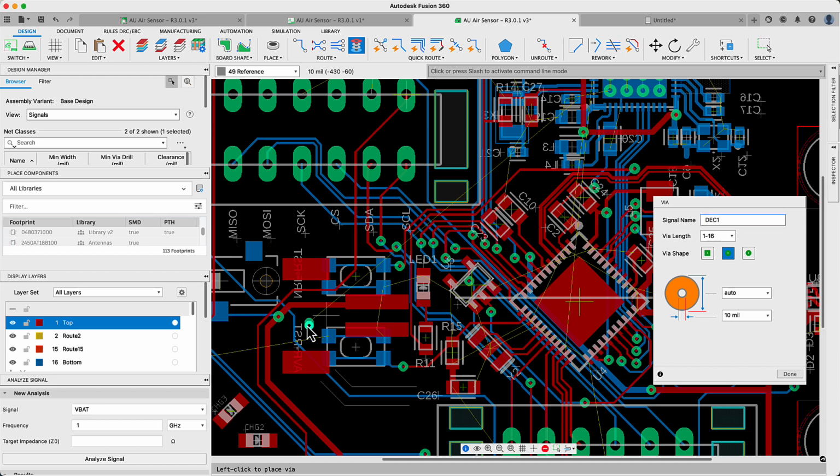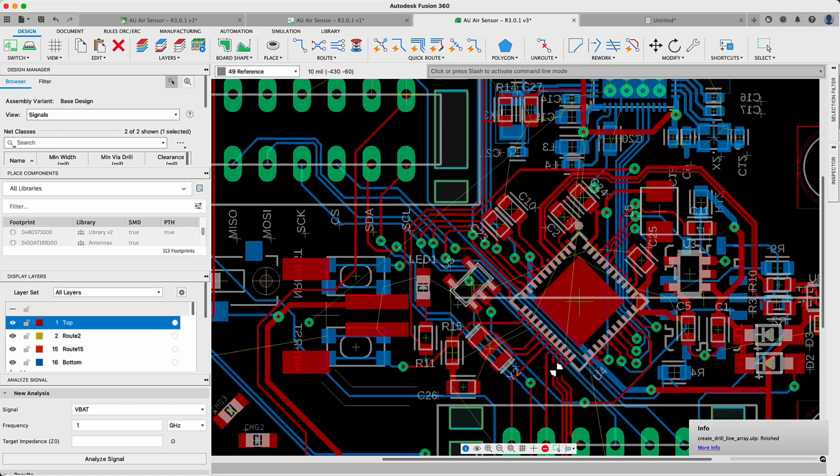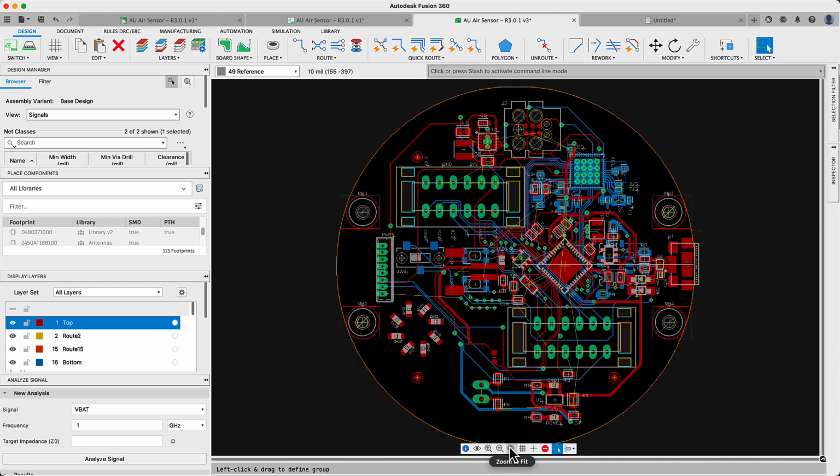You will now notice that the dialog box includes a name field. Type in a new name for your via or select one from the autocomplete list. This time-saving feature will help you select your via signal name without having to search around your design for the correct name.